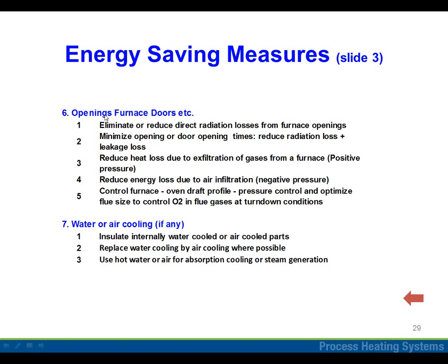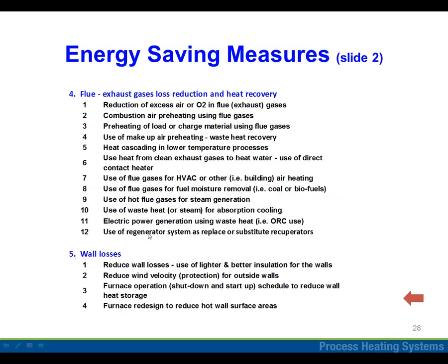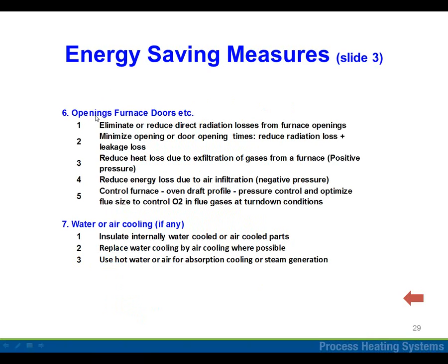Next one is the wall losses. Previous slide, Sachin, for a second. Okay, again, reduce the wall losses, reduce the wind velocity, shut down the furnace. These are some of the things. But the only thing that can be done is, while you're rebuilding the furnace, use the lighter and better insulation. Next. Sachin, next. Opening losses. This is one of the major areas where people have no idea how much heat they are losing by direct radiation. But it's amazing how much heat goes out on the radiation. And we'll talk about that in the...